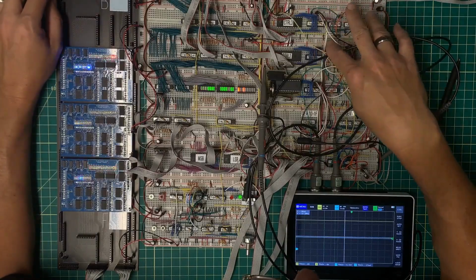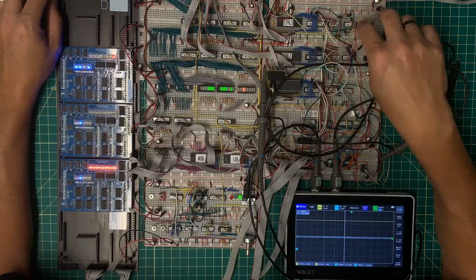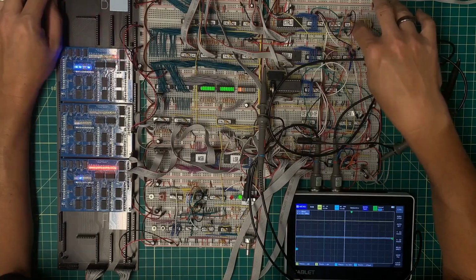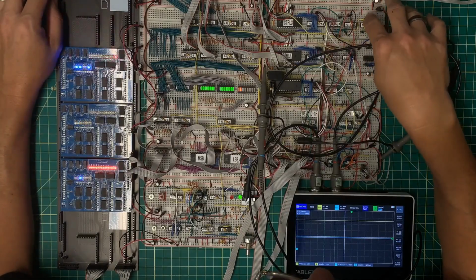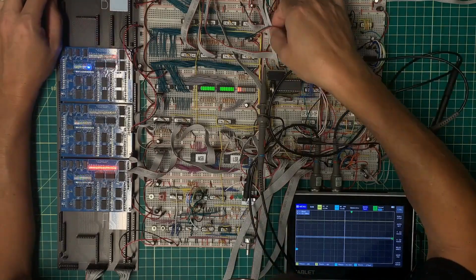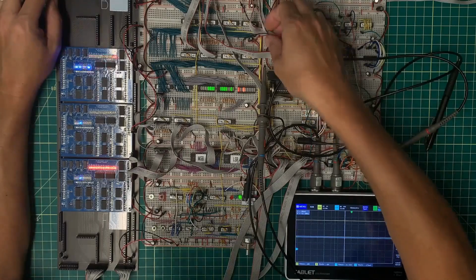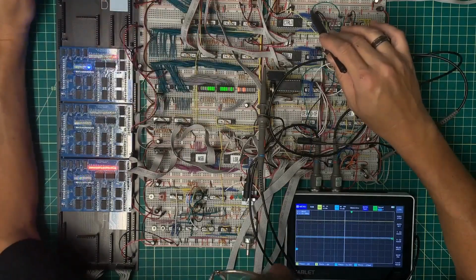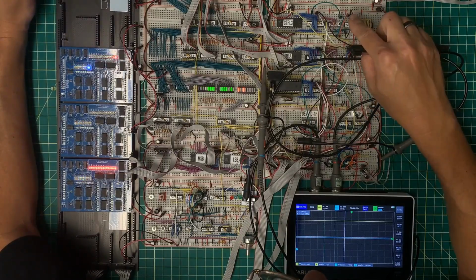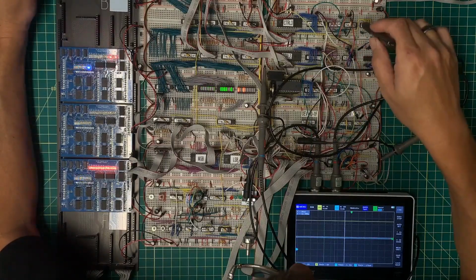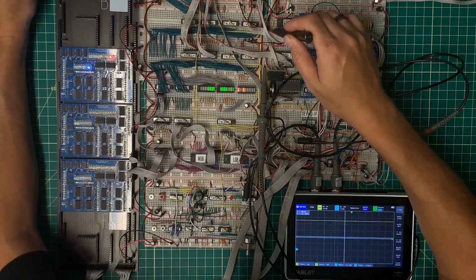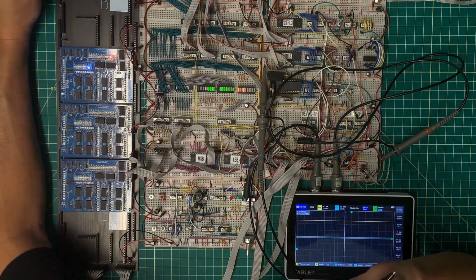And so tracing those, these are NANDed. There's an inverter that goes on here, and then NANDed with a bunch of inverted, significantly delayed clock. So I believe my program counter has some extra delay built into it, but it appears to be NANDed with the results of all of this delay here, which is driven off of the actual clock.